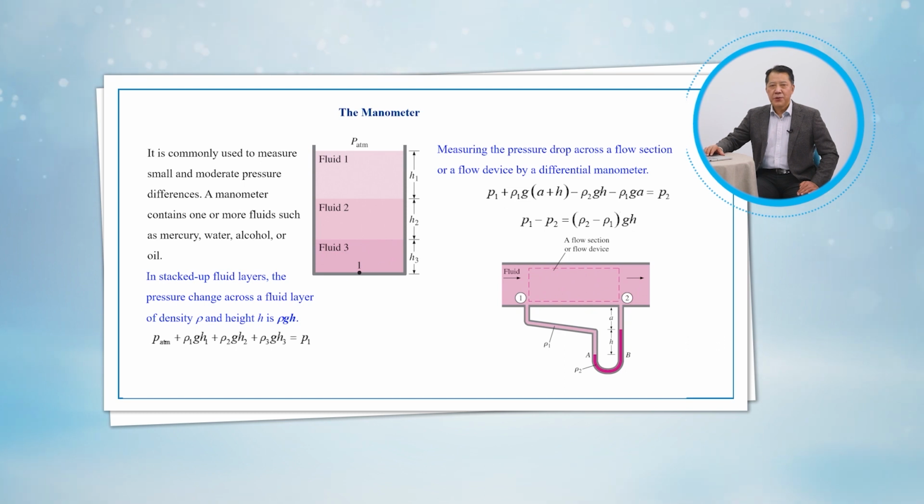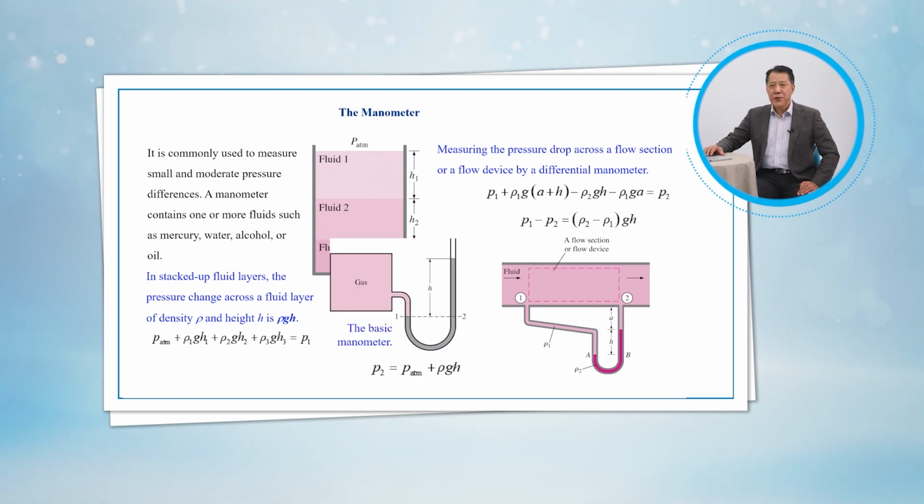to P2. Consider the manometer shown in the figure that is used to measure the pressure in the tank. Since the gravitational effects of gases are negligible, the pressure anywhere in the tank and at position 1 has the same value.